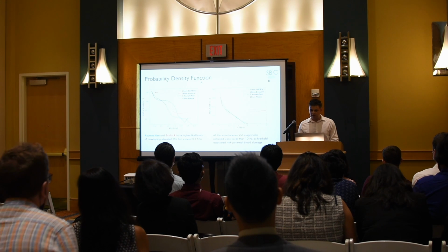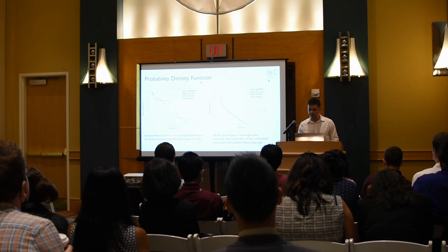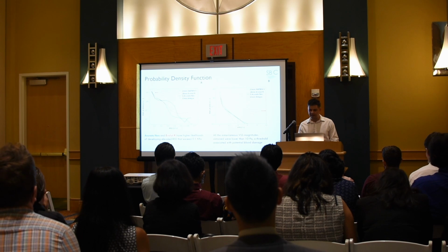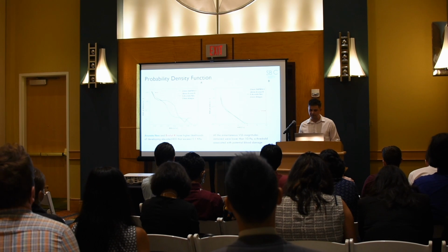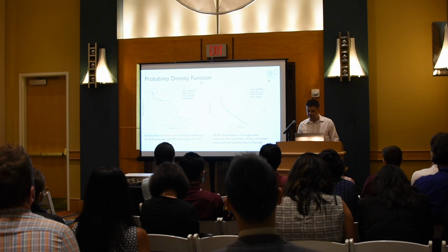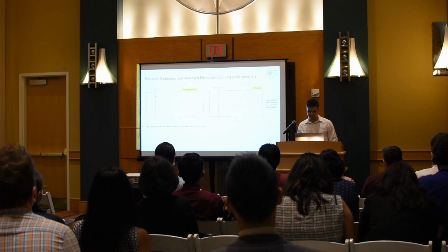And to evaluate the actual shear per unit area that is experienced by blood elements, we calculated the instantaneous viscous shear stress for each of the flows. All the instantaneous viscous shear stress magnitudes obtained were lower than 10 pascals, which is the threshold associated with potential blood damage.